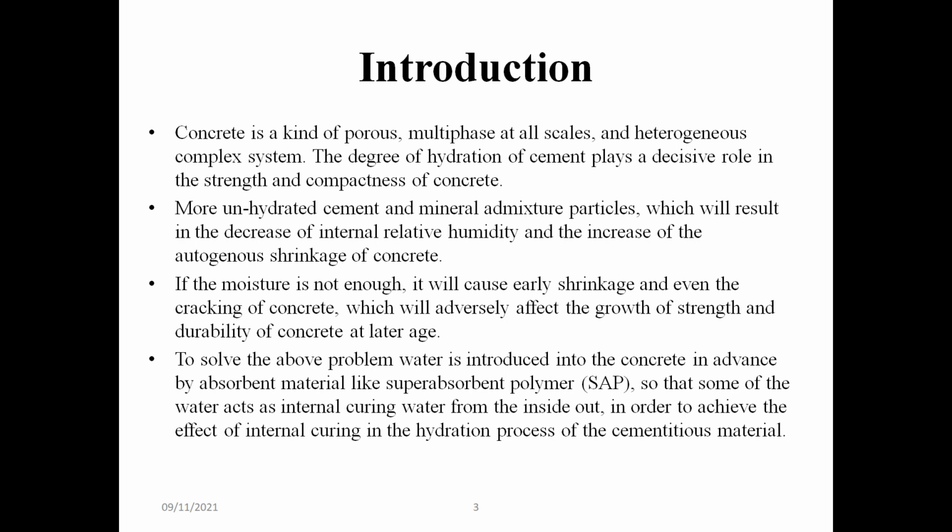To solve these problems to some extent, we are trying to incorporate the super absorbent polymer inside the concrete, which can act as an internal curing agent and freeze resistant agent inside the concrete. Thus, in order to achieve this effect, it releases water, creating an internal curing effect in the hydration process of cementitious material.